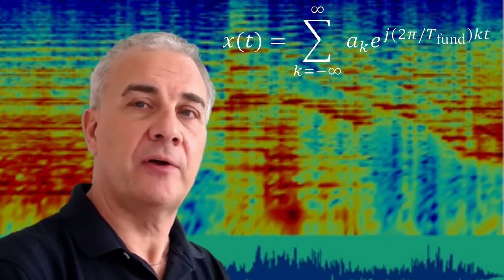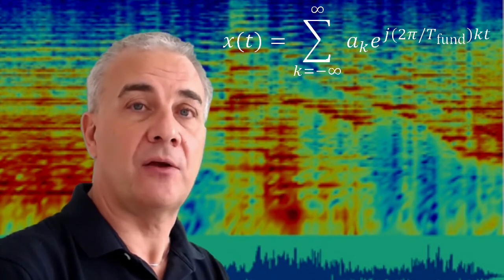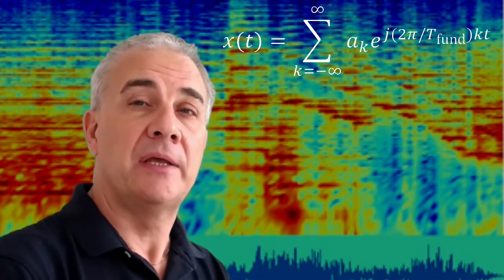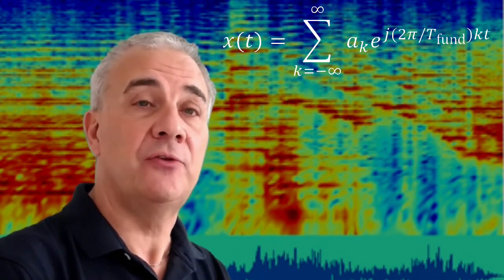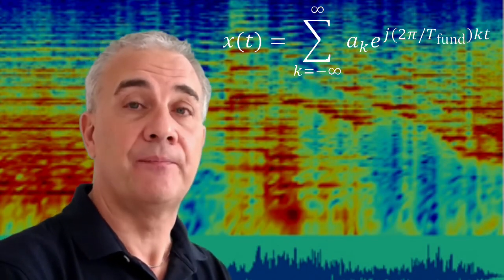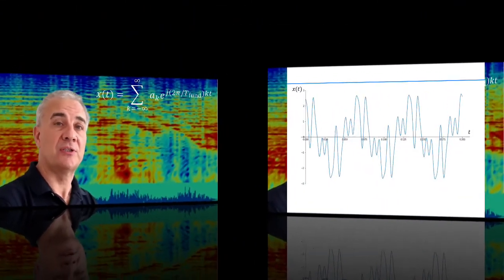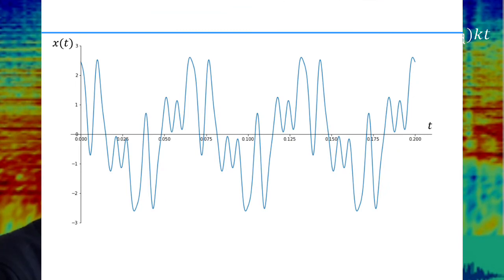If we try to find out if a cosine with a particular frequency occurs in a signal, then we can try to match that cosine to the signal and see if it fits. Here's an example for the simple signal that we started with. If we take a cosine with frequency 15 Hz, then the match looks like this. Now if we multiply and integrate the signal and overlay cosine, we get a number that is directly related to the amplitude of the cosine of that frequency.